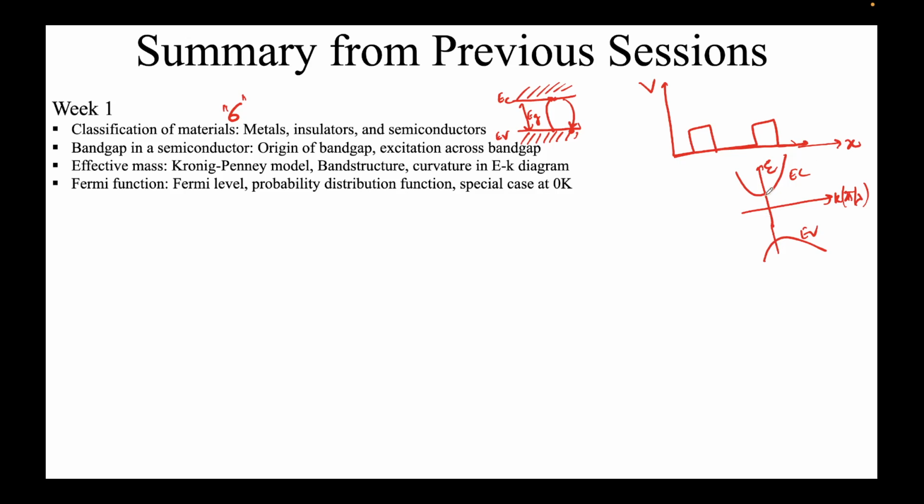This effective mass is a very useful construct in the context of semiconductor devices, because now we need not worry about quantum mechanics, orbital overlapping, and so on. Whenever we come across the mass, we can use all the classical equations, just replacing mass by this effective mass. That's all.